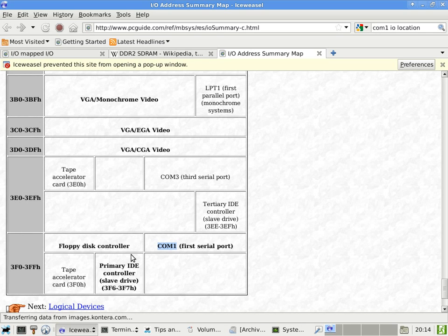So with the Intel architecture, this space is entirely separated from memory. What that means is we have one set of instructions to access memory. Okay, we have the move instruction that can move from register to memory location and so on and so forth. But the move instruction cannot touch the I/O space at all.